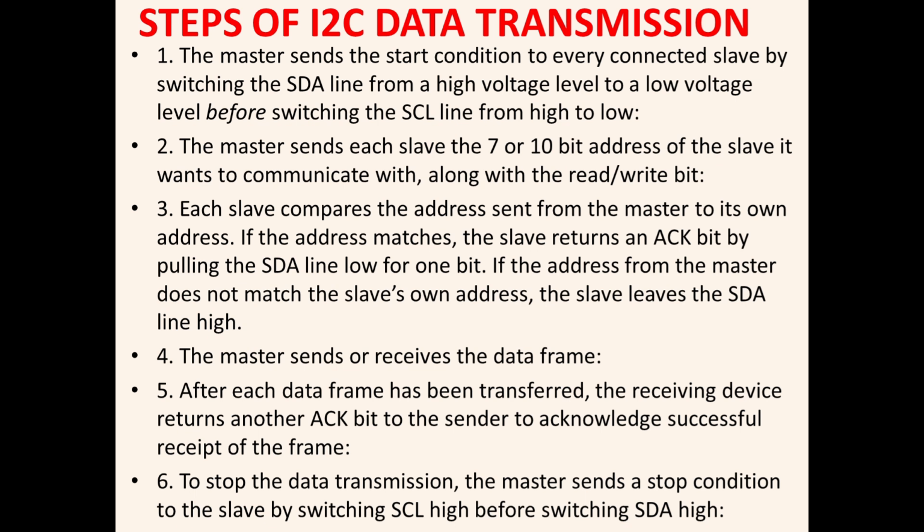In that manner, the master will initiate the transmission or reception of the data frame. But in the fifth step, if you have multiple data frames, each data frame has to be transferred and must receive an acknowledgement bit, to or from the master.